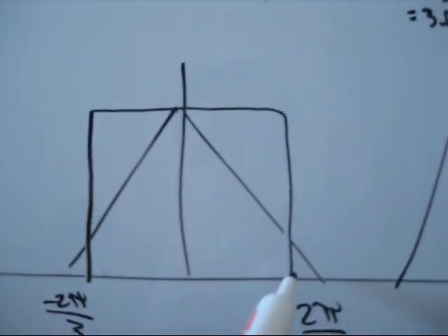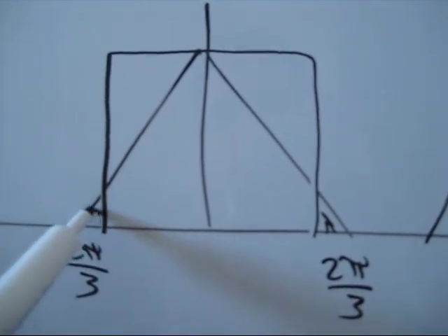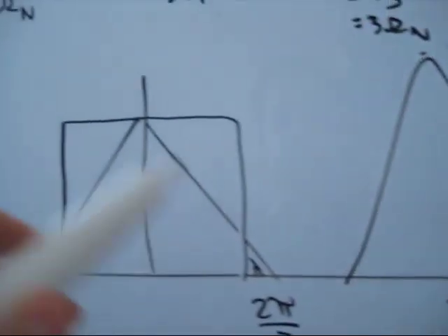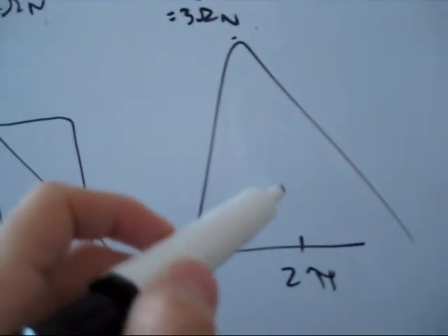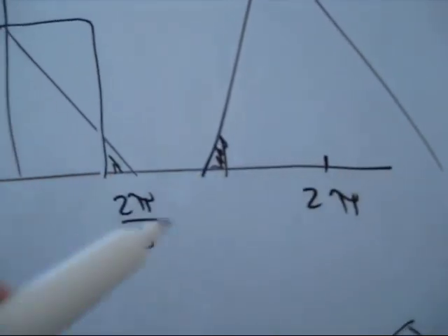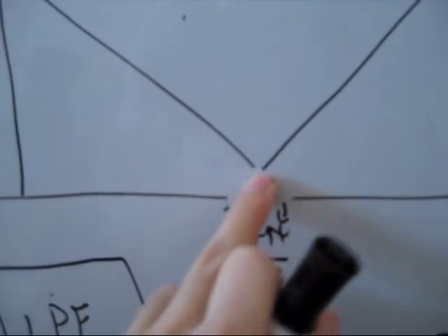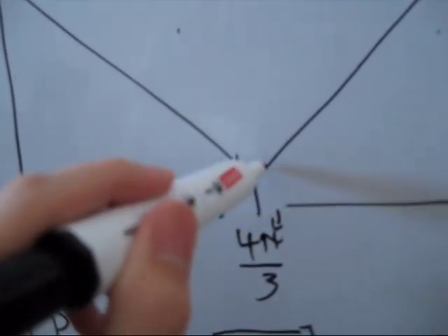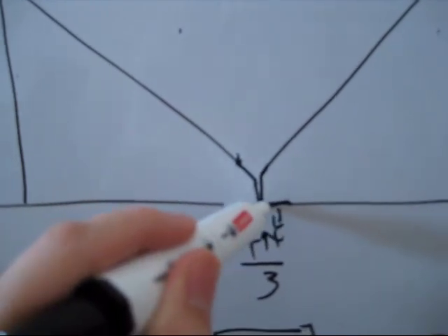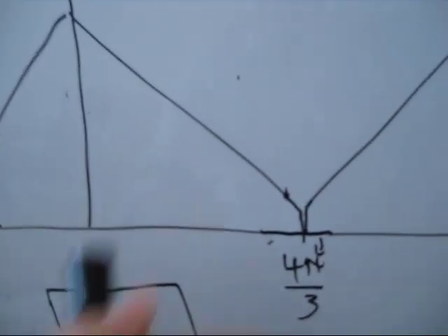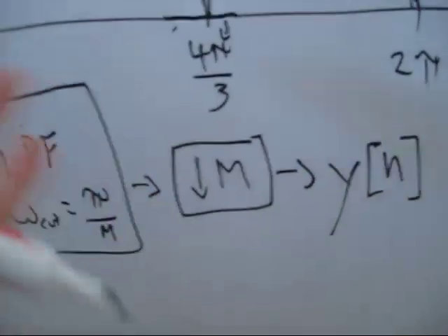So you would cut out that bit and that bit, and of course, there's replicas for the filter also, so that it would cut out that bit and whatnot. But we went over that last time. So you get rid of all that, and then you don't have these anymore because it'll look like this, and then infinitesimally close to it, like so. All right, no more aliases, and of course, repeat it all around. So that's how you do downsampling.